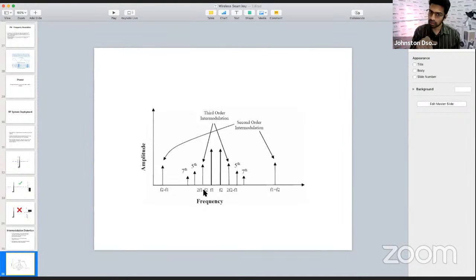Then you go into the receiver, and in Sennheiser you go to easy setup and then scan new list. When you say scan new list, it will start scanning, from 470 megahertz to 560 megahertz. I don't know if you can see it very clearly, but I'll try and see if I can use my iPad camera for this.